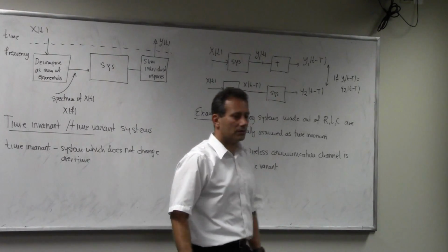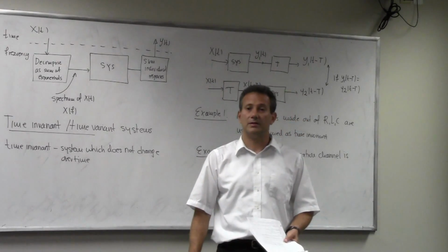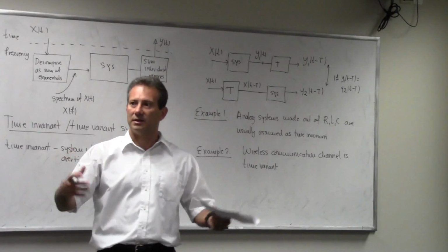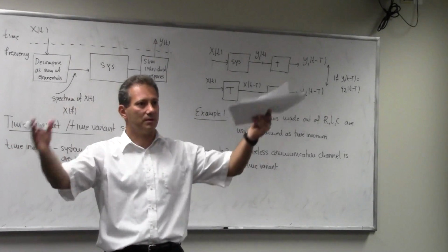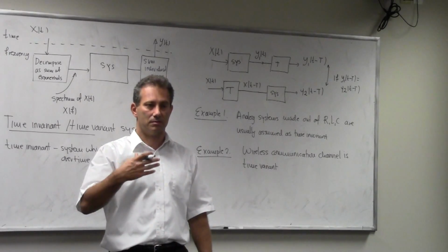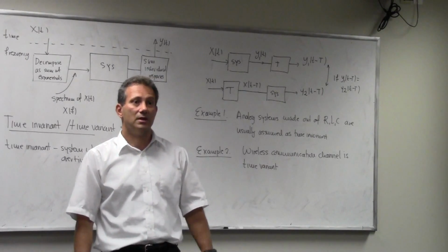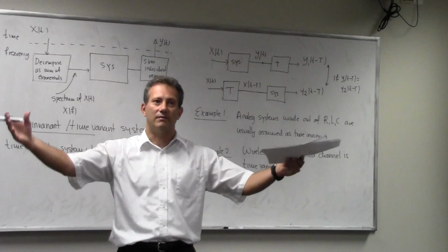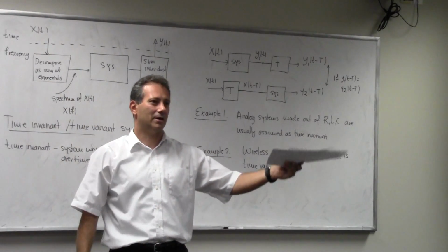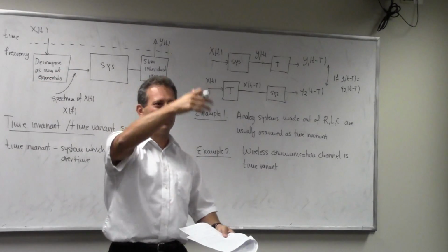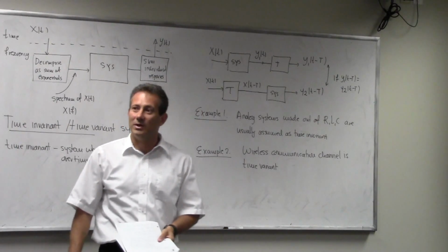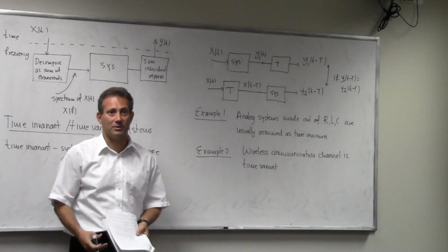Why? Because first of all, there's an element of mobility, right? If I transmit from there and I'm moving over here, then the signal that reaches me always travels different paths and reaches this point in a different way. Therefore, the channel changes itself. Even if I'm sitting still, the environment is in motion, right? So the fact that there's a truck passing by, or the bird flew in between, or there's leaves on the trees that are being moved by wind, all of that will change the properties of the channel.